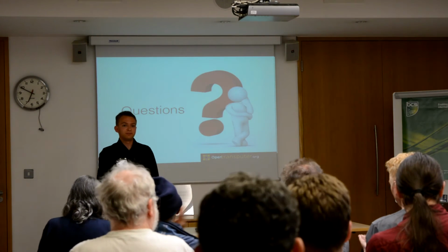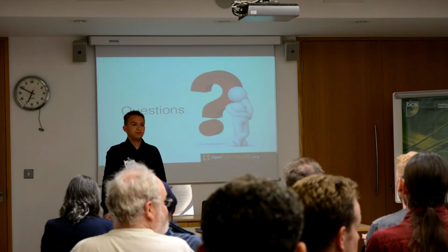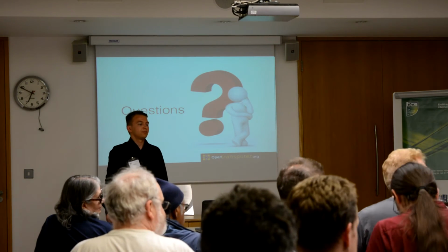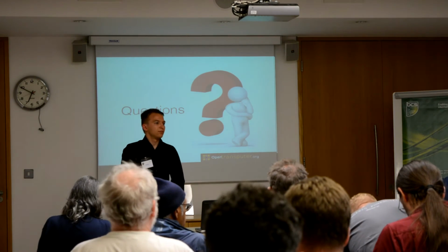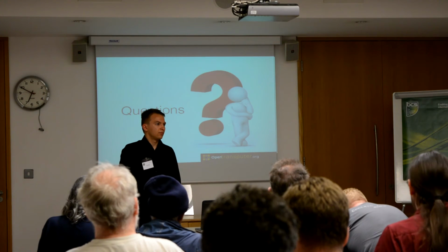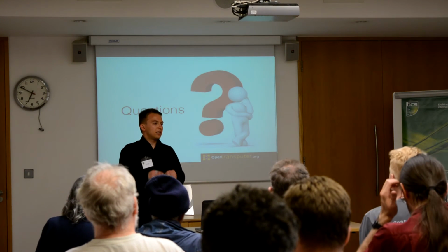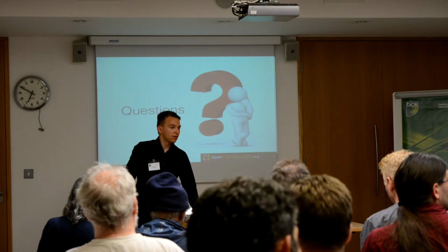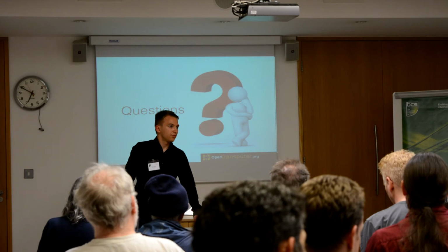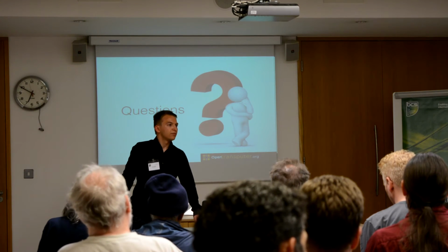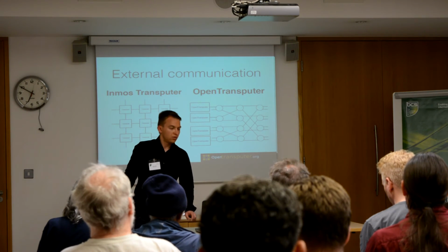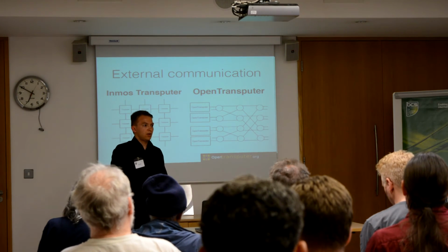Any questions? So in your switching framework to route things between processes, it's a binary tree hierarchy, right? It is recursive, yes. So how do you avoid starvation in the switch architecture? For example, if one processor tries to send a lot of data quite far across the switch, you need to traverse to the root and back, and that blocks other processors traversing the same path.